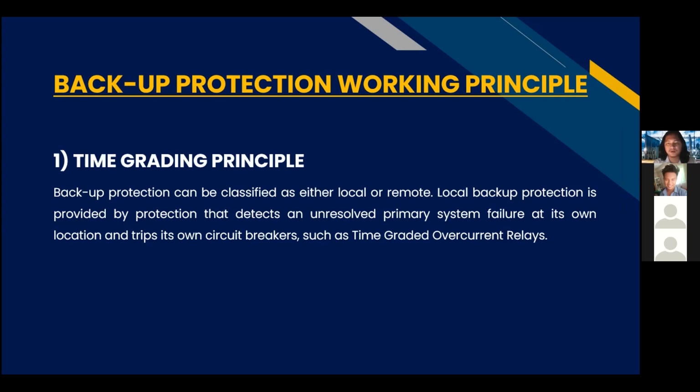This principle is to grade the operating times of the relays in such a way that the relay closest to the fault spot operates first. And if the first protection fails, there is a time lapse between the first and the second protection in order for it to activate. If the fault doesn't stop within the time lapse, the next protection will operate.